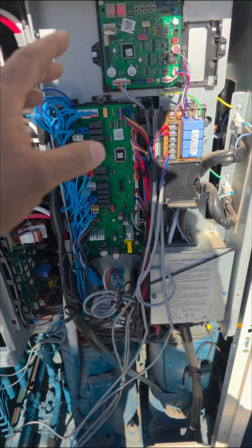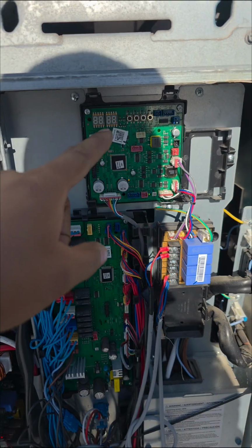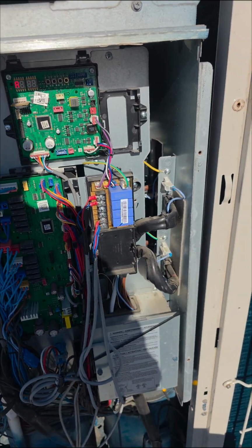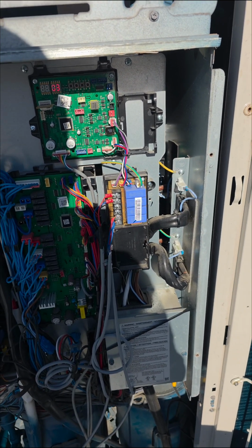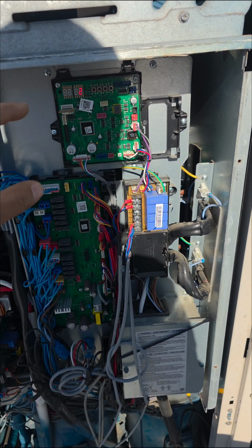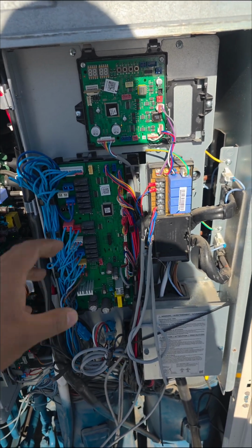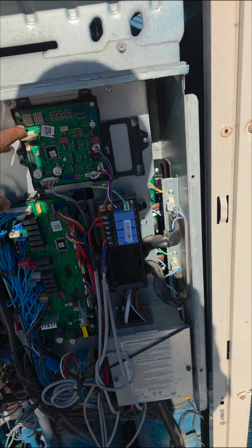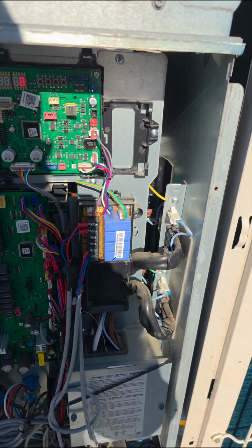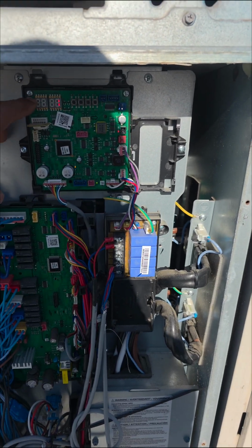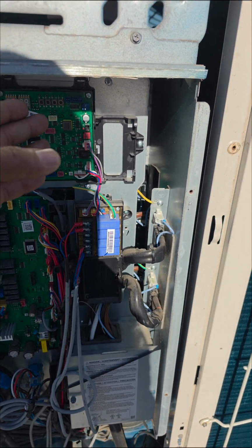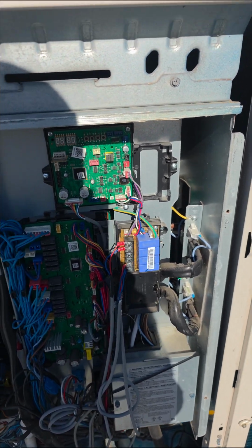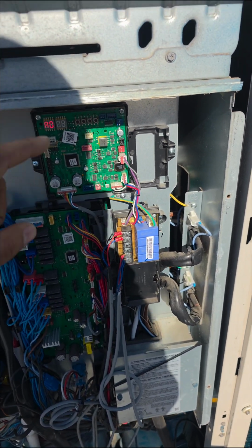So the fault code that we're intermittently getting, I'm not sure if you guys are able to see the segment display over there. However, we're getting an E206 error code, which is communication failure with the main board to some of the slave boards. But then we also have a subcode, so it's very important when you're dealing with the E206. The unit will display an extension of the error code. It will be either C001, C002, C003, and so on. So we've got an E206 and we got a C002.